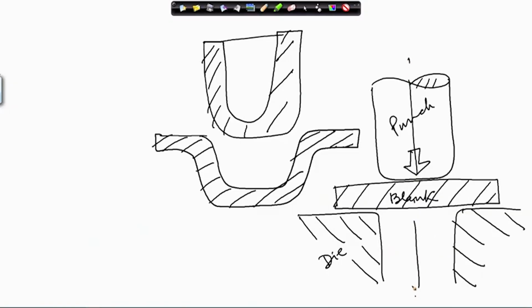So, this is one example of metal forming. You can deform a body into shape. You are not having removal of material in the form of chips, you are not having melting, you are not having joining, but you are basically deforming by plastic deformation. Please note that had it been elastic deformation, it would have sprung back into shape. So, it is definitely plastic deformation, which means that once it is deformed, it cannot come back to the original shape.